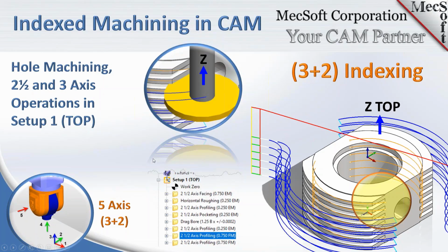And here we're looking at each of the orientations and what the machining jobs that you need for this particular orientation. So I mentioned the setup 1 is the top by default with your Z pointing upward, and we're performing facing, we're doing some roughing, profiling, some boring, etc., to machine all of the features that we can get to from this top side orientation.